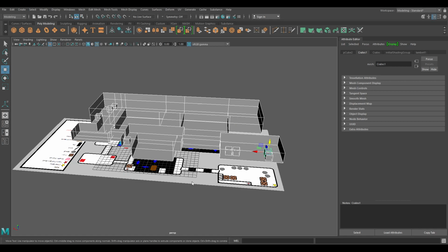If you leave the scale factor as is, it can cause a few issues. So what I would recommend doing is just dropping into this bit before you export it, untick automatic, and change your file units converted to centimeters. That way, your scale factor goes to 100.0 and everything should be fine. So I'm going to drop this on my desktop. I'm going to call it level plan. Doesn't like spaces, does it? So I'm going to call it level 1. That's what we'll call it, level 1. And we'll go export, and we're ready to go.